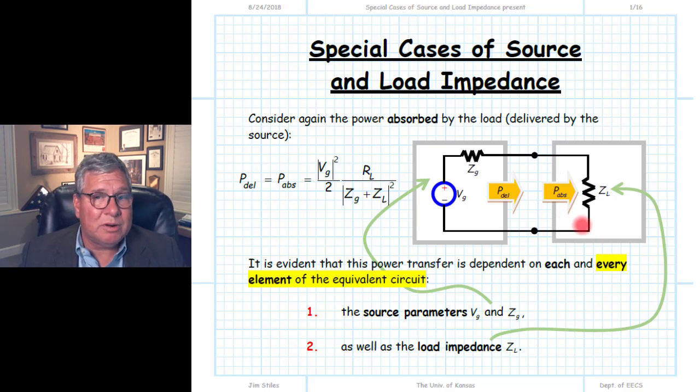And if those devices are linear and time invariant, we can replace them with an equivalent circuit, which is simply an impedance, its input impedance. And that characterizes everything that we need to know about that blue box, regardless of how complex and how many elements might be inside. We really just need to know its input impedance. And so we replace this very complex and impressive set of electrical engineering with an almost trivial circuit.